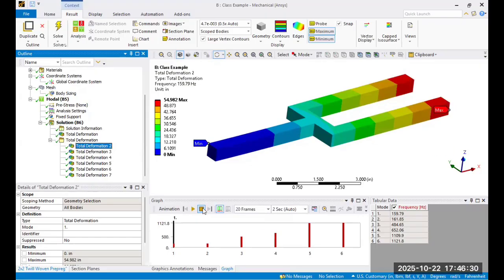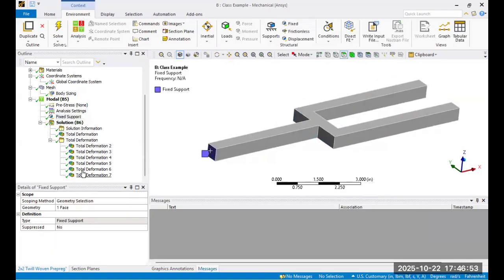And hopefully the next project is actually looking at a tube. I think that's an excellent example. We can do it pressurized, unpressurized, so they can see the pressure stiffening. When you have pressure inside a tube, you'll see frequencies are higher. But when you have no pressure inside a tube, you'll see the frequency will be lower. And we can maybe look at different supports. Maybe that's just an idea. But very important in design, and that's why we want to bring this in. And I'm glad you went through this today.